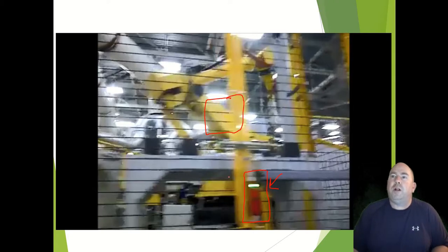So you need to push a button, and this will not unlock unless this robot has completed its task and is sitting back at a home position and is ready for someone to actually enter the cell, and then this would unlock and you'd be able to open that door. Opening that door would then break all the safety. But we don't want you to be able to do that while this robot is in motion.